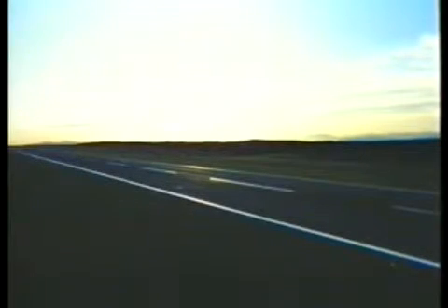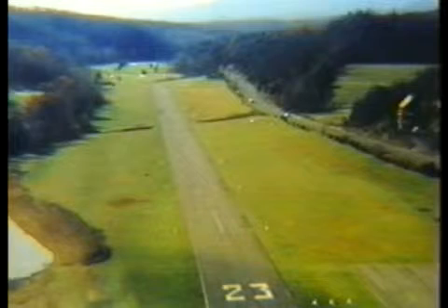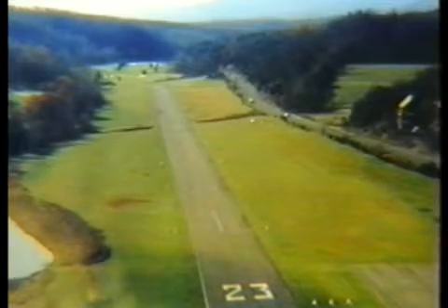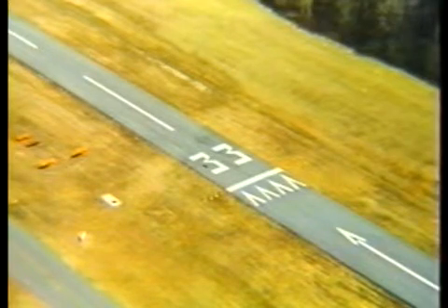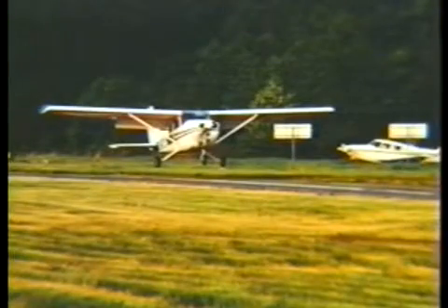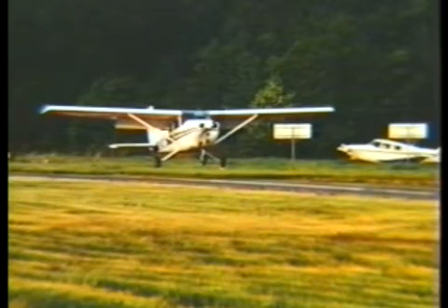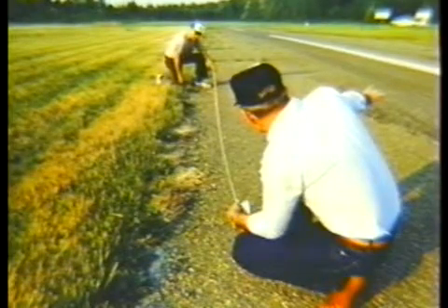Now, earlier we mentioned that runway length is also a factor in landing long. Oh, I know that you're not going to land a jet on an 1,800-foot runway. At least I hope not. But did you know that you can turn a 2,100-foot runway into an 1,800-foot runway just like that? That's right. One way, of course, is to have a displaced threshold. But you knew about that, didn't you? However, did you know that if you fly a non-standard VASI, and that's the homemade variety, even if you're flying the right airspeeds, you'd also better have a good idea of where the airport operator has located his aim point for you.